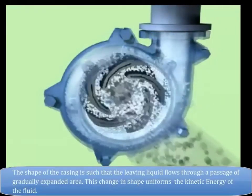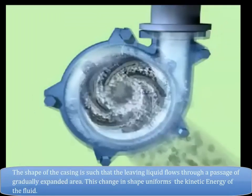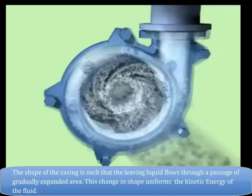The shape of the casing is such that the leaving liquid flows through a passage of gradually expanding area. This change in shape converts the kinetic energy of the fluid into pressure energy.